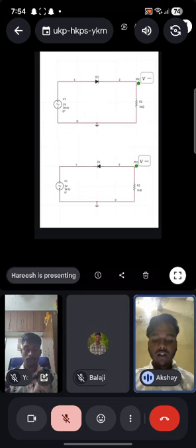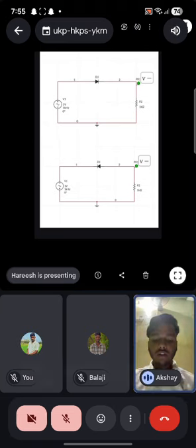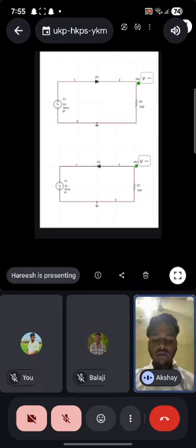A diode or PN junction is reverse biased when the negative side of the external bias voltage is connected to the P region of the diode, the anode, and the positive side is connected to the N region, the cathode. In this condition, the current can't flow through the PN junction.